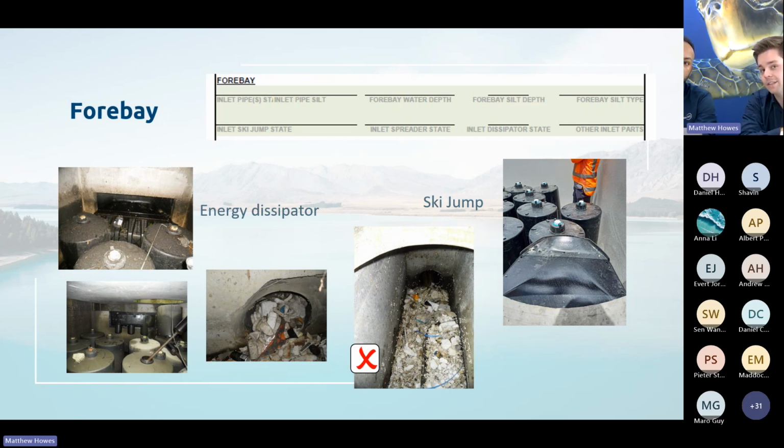And as I say, that's an excellent example of why pre-treatment is really good and reduces the maintenance burden, because pre-treatment would remove all of this from the inlet bay, reducing the maintenance requirements of that StormFilter. Definitely. Yeah.